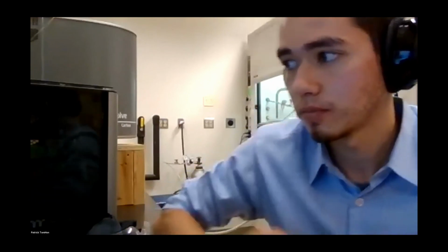Let's see. All right, so the first three questions are very similar, so I'm going to try to combine them. Can you comment on the current and perhaps ultimate limits of your setup in terms of the fluid flow rate, the parahydrogen pressure, and the temperature? Yeah, so the current limitation of the setup in terms of pressure is 100 PSI. But the only limitation of that is actually the glass flow cell. So we're talking to Wilmad to try and get a flow cell manufactured that will allow us to go up to 200, 300 PSI.